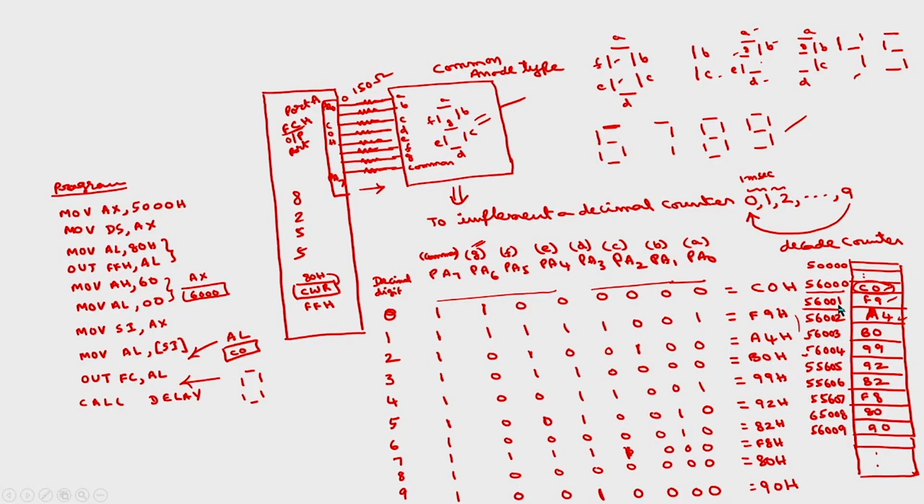So you have to simply increment AL, INC AL, compare AL with 09. So up to 09 we have to increment this. We will compare with 0A otherwise, because 9 also you have to display, right. So you take one above this, 0A, jump not equal,